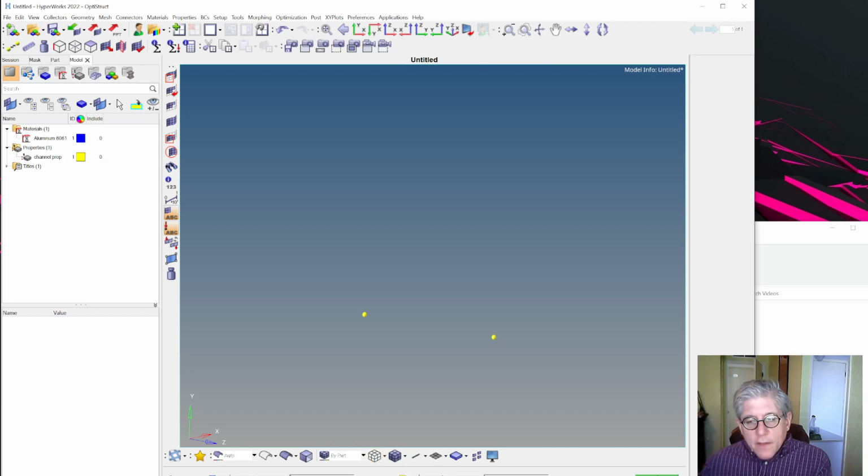And now on the left are the terms that Hypermesh refers to it. And then it says, okay, if you pick a mass element in Hypermesh, I'm going to make this type of OptiStruct or Nastran element. So these values change depending upon what software you're using. If you select ANSYS in the user profile, you will get different words here because it will use the ANSYS class. So we're going to use rod elements, and you can see here the rod element defaults to a C-weld element, which is a type of Nastran or OptiStruct element. We want to change that to be a C-rod.